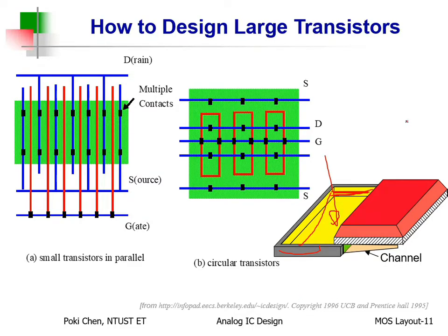However, for the other side wall, close to the gate, you don't have a PN junction. Why? I told you already. To raise the gate voltage to connect source and drain. Alright? So here it is N plus, and after strong inversion, actually the channel is also N plus. Alright? No PN junction at all. So it means the side wall just beside the gate actually has much less parasitic capacitance. That is the key point.